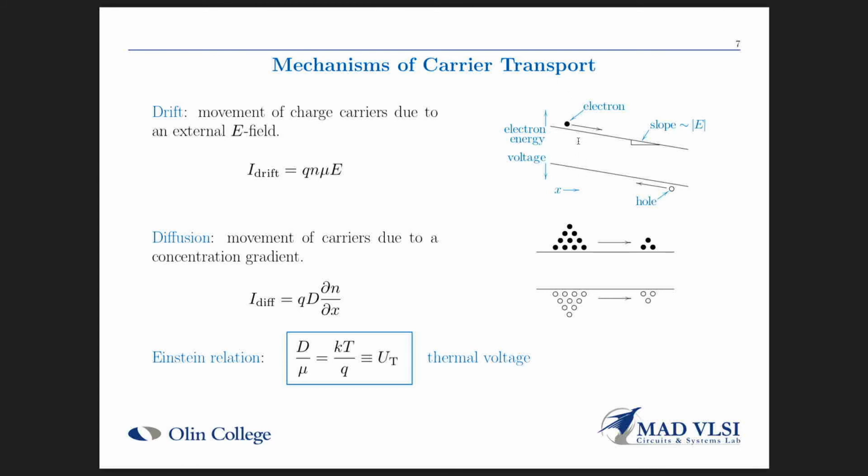And this range of energies in between here is called the forbidden band, or the band gap. So electrons don't normally hang out here, holes don't normally hang out here. And this is roughly the gap between these two energy bands, that 1.1 electron volts that I mentioned earlier for silicon. Holes bubble up and electrons go downhill on a picture like this.